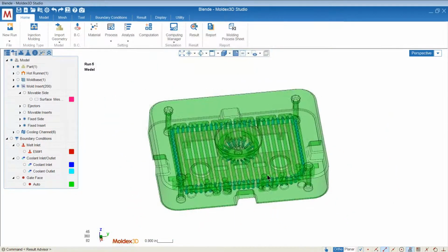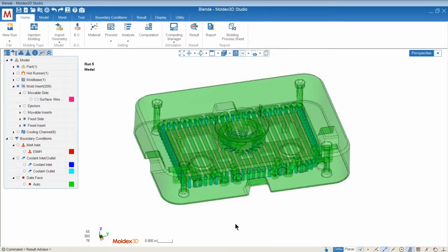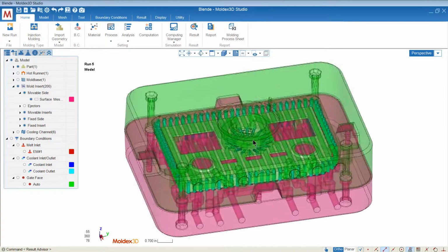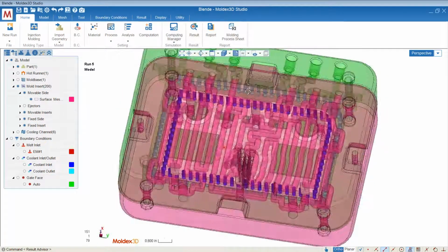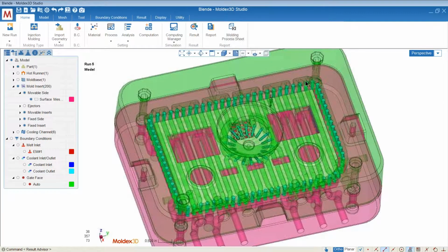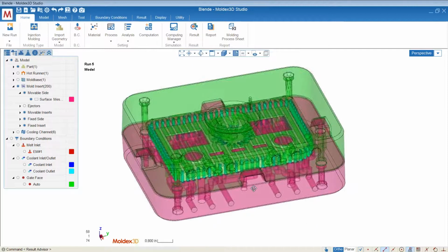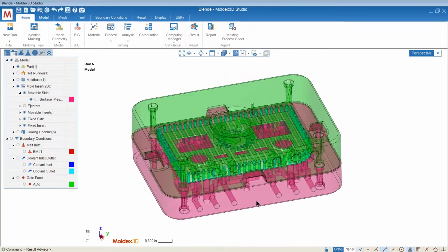So this is what I call conformal cooling. What I showed you in the lesson was a simplification of what conformal cooling can be. This is the ultimate in technology nowadays, that you can really import not only conformal water lines, but add pure copper inserts in critical areas to create what I call a super duper conformal cooling setup.